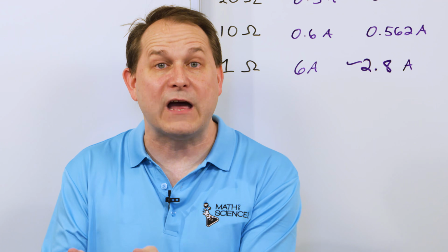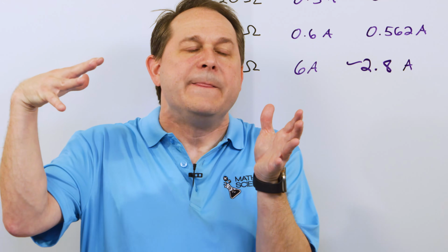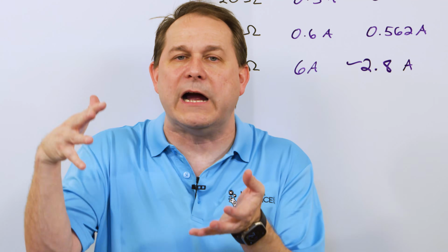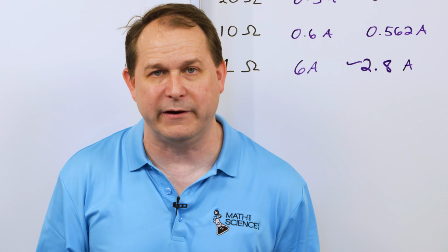The 6 volts that you thought you had, you didn't really have it, because as soon as you start asking too much current of it, then the chemistry just can't keep up inside. The battery voltage drops, and that's why it can't supply the correct amount of current.